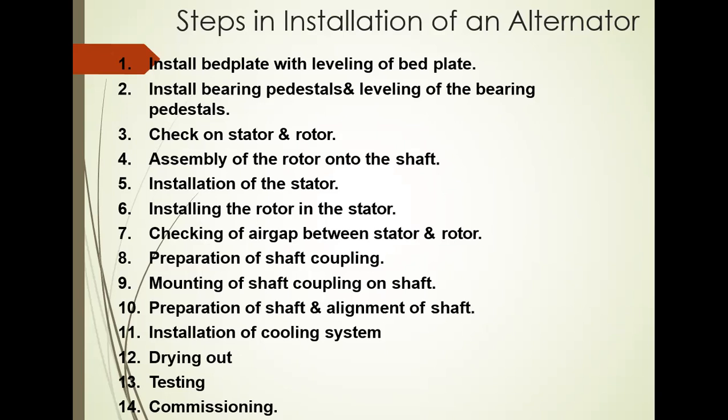After that, install bearing pedestals, leveling of bearing pedestals. Then check the rotor and stator, whether everything is in good condition or not. Assembly of the rotor onto the shaft. Installation of stator. Then installing the rotor in the stator. Checking of air gap between stator and rotor.